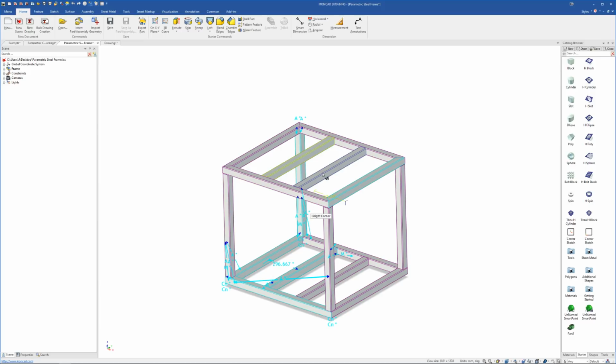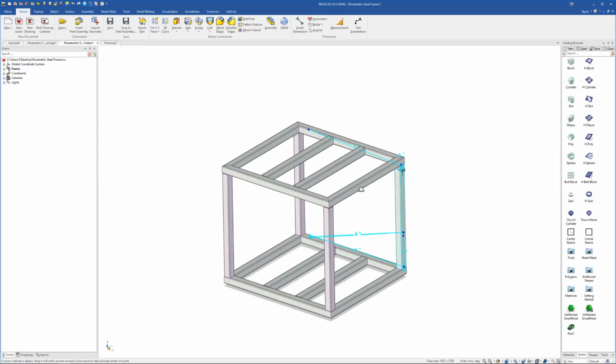Stuff that isn't patterned is a little bit easier. But if it's an assembly, then it's even harder. You've got to click and then click again. So it makes it a little bit hard to select down if you have lots of levels in there, like patterns and assemblies and things. So what's really useful to know about is the selection filter down the bottom here.